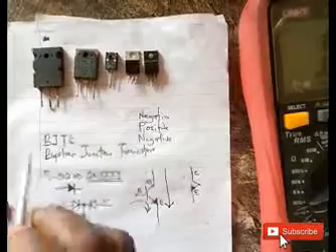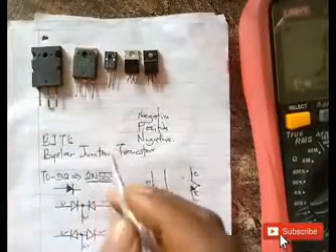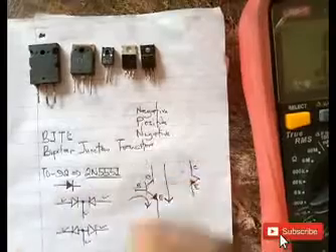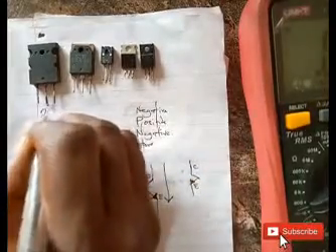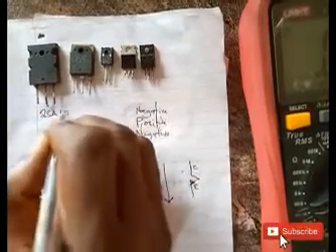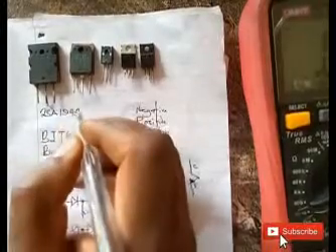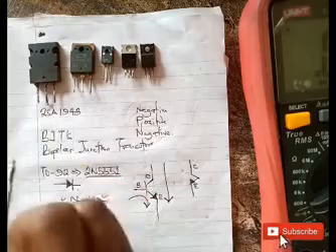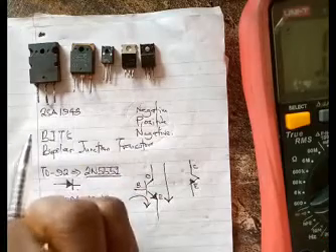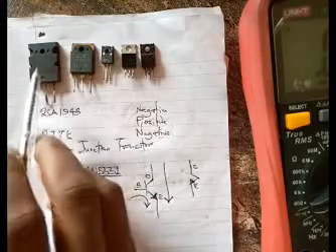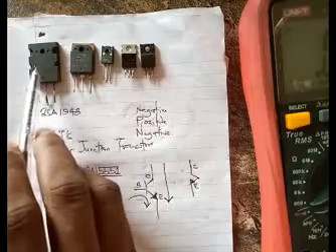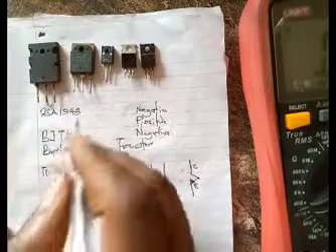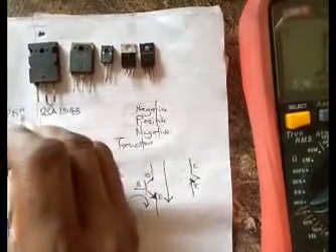All right, now this is 2SA1943. It's written on it. Just in case you can't see it, let me write it out. The part number is 2SA1943. Now another key I want to show you is that from experience I found out that any part number that starts with A before the number is usually a PNP transistor.